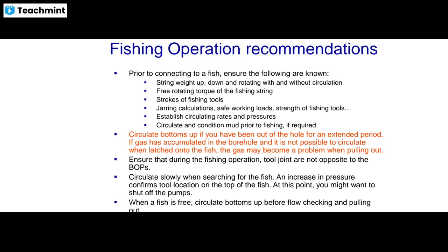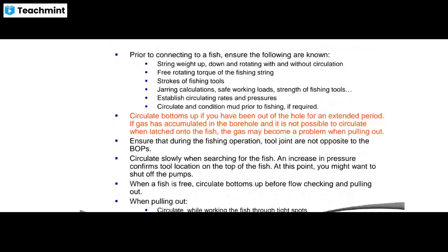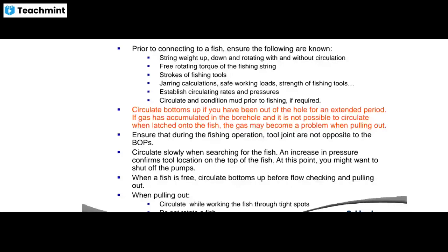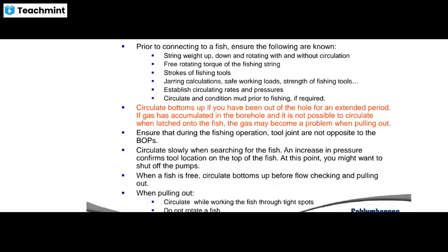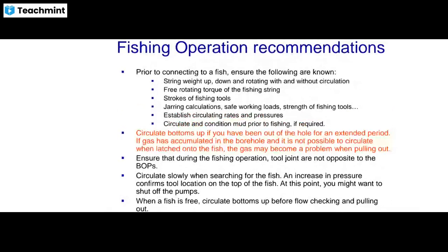So when a fish is free, circulate bottoms up before flow checking and pulling out. When pulling out, circulate while working the fish through the tight spots. Do not rotate the fish. Then also circulate bottoms up if you have been out of the hole for an extended period. If gas has accumulated in the borehole and it is not possible to circulate when latched into the fish, the gas may become a problem when pulling out.